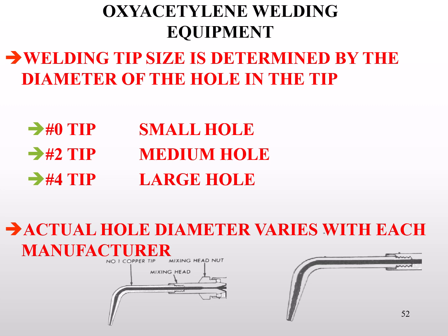Depending on the manufacturer, you would select a tip number, which determines the hole size, and you would select that based on the metal thickness. The thicker the material, the more heat is needed to get it into a melted state. So therefore, we go up hole sizes for thick material, we go down hole sizes for thin material. Each manufacturer sets that. Unfortunately, they don't all match.